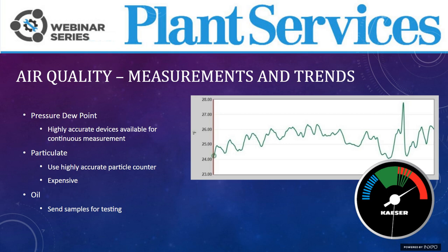Alarms and warnings can then be sent to ensure that the plant addresses the issue. So that could be a high alarm or a high-high alarm. So, maybe a warning first and then an alarm second. What they do with the alarm, that depends on what the critical nature of your business is. If it's a warning, perhaps it does nothing. If it's an alarm, perhaps it shuts the station down or closes a valve.